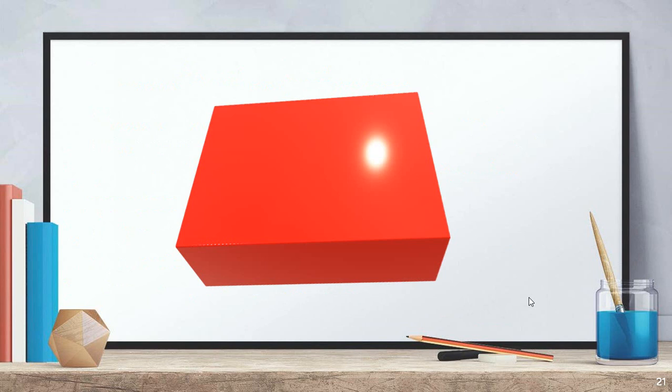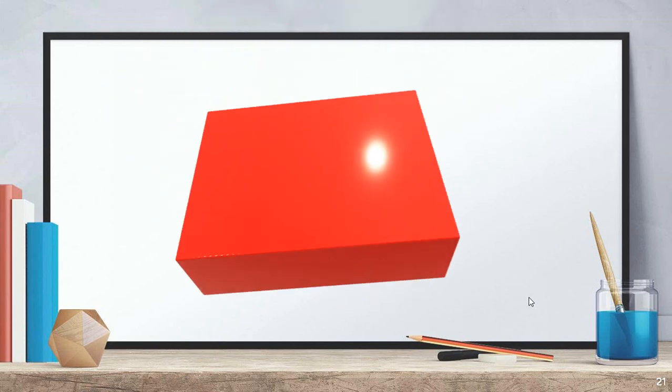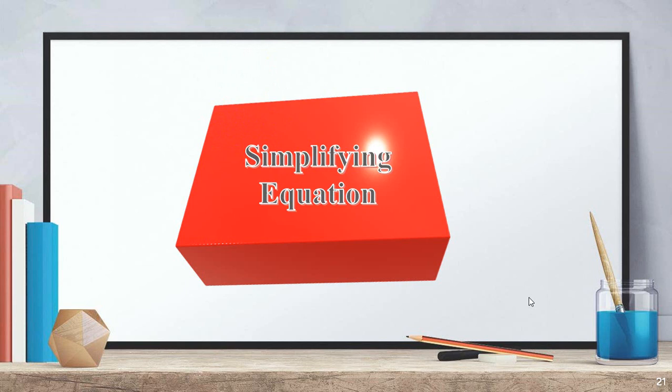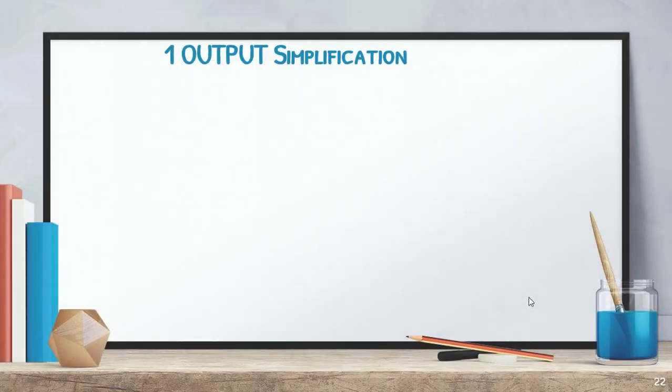Now we can move on to the third and last part of the KMAP. Once we are done grouping, how do we do the simplification of boolean expressions? After grouping, from that grouping we can form the equation and do the simplification. Let's take an example of one output simplification. If any expression contains only one minterm of the canonical equation, then how can we solve it in the KMAP? In the first example, we have taken summation of m 0.